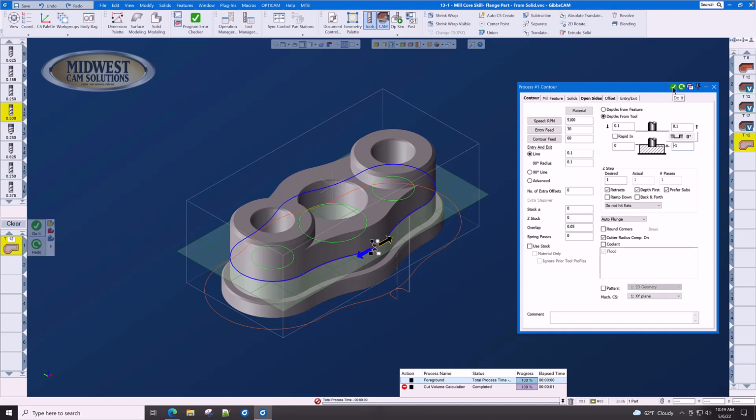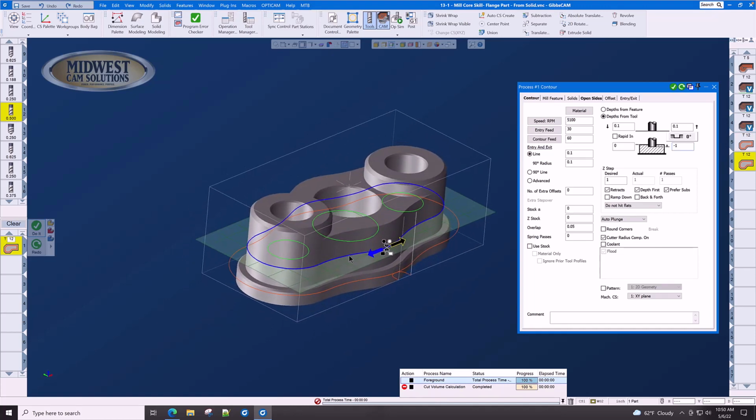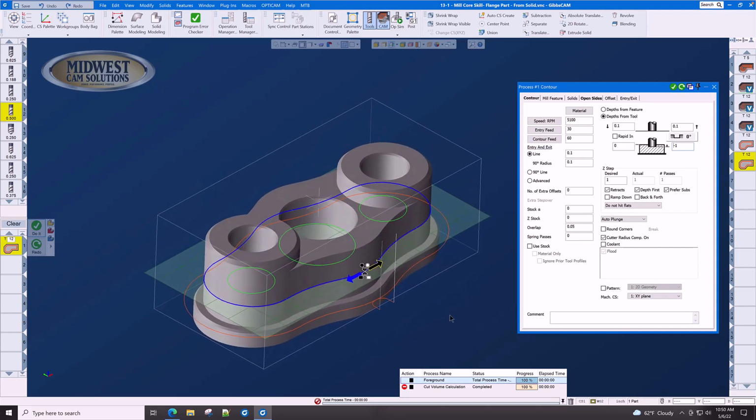When we press Do It, we get a toolpath. Notice that the toolpath is not affected by the height of the profiler. The profiler simply gets the geometry for us so that we can make the cuts. Now, let's go up and get the two